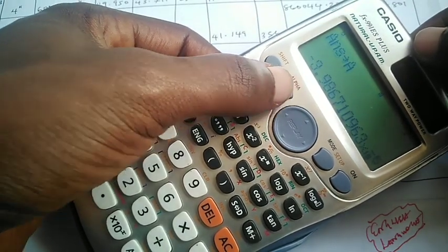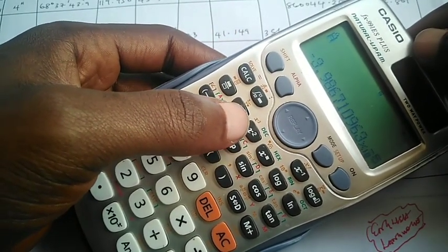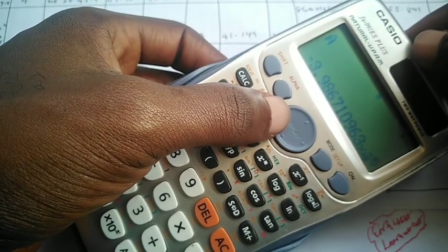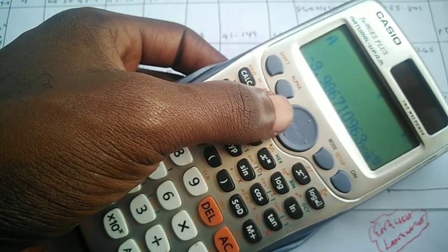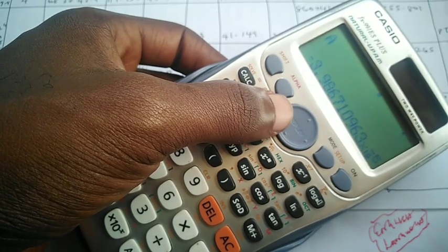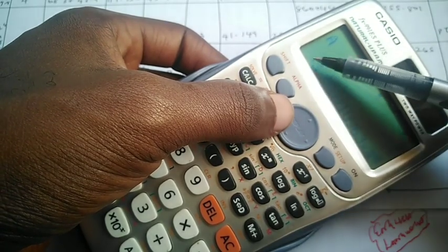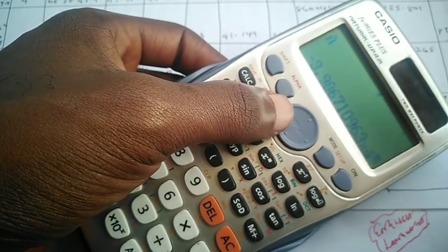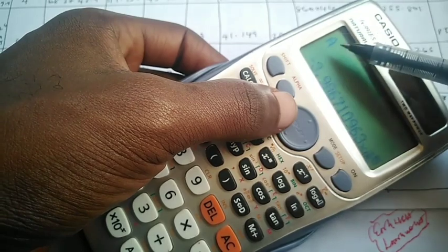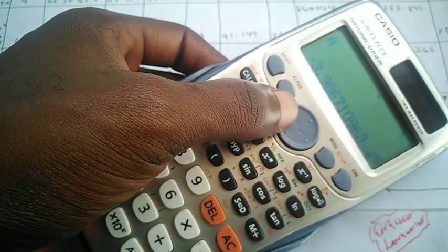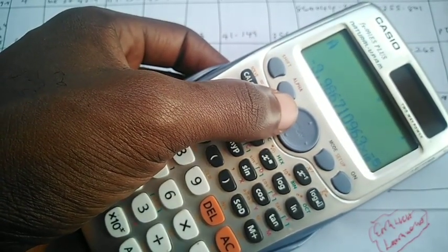By the time we recall alpha A, the answer comes out. So this is what we are going to use to multiply the arithmetic sum for each of the stations. By the time we multiply the arithmetic sum of each of the stations, we are going to get the correction we are going to apply to the coordinates on that particular station. So you can see it's very simple. The first thing you are going to do is just get the quotient and save it on your calculator, so you don't have to press that over and again. I think that's a very good shortcut. So now we've stored it as A, and we are going to be multiplying it by the corresponding arithmetic sum for each station. So how do we go about it?